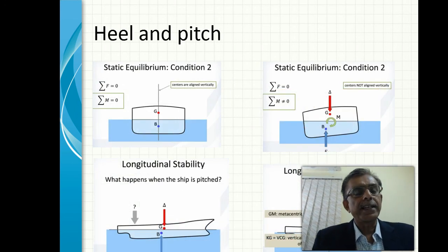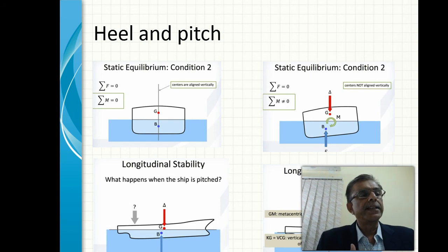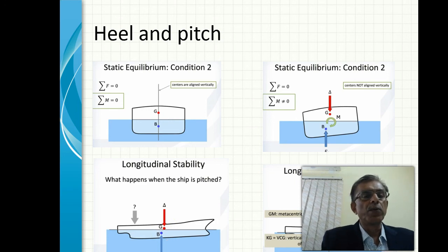Now, as much as the hydrostatic part of the transverse stability, there is the static equilibrium in terms of the trims. Again, there is another subject on stability, and I will cover this at that time, but it is important to understand that the pitching or the trims of the ship happen because of the weight of the ship, the center of gravity, and the center of buoyancy. This gives the moment which will right the vessel when it moves away.